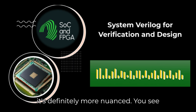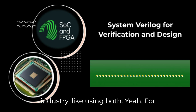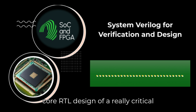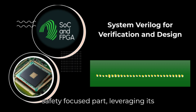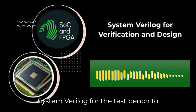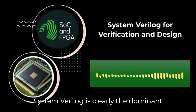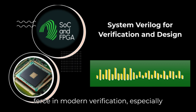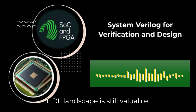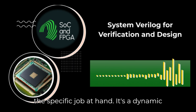Oh, it's definitely more nuanced. You see mixed language flows quite often in the industry. Like using both? Yeah. For instance, a team might use VHDL for the core RTL design of a really critical safety-focused part, leveraging its strong typing. But then they might use SystemVerilog for the test bench to verify that VHDL block. So, while SystemVerilog is clearly the dominant force in modern verification, especially for large SoCs, understanding the whole HDL landscape is still valuable. Engineers often pick the best tool for the specific job at hand.